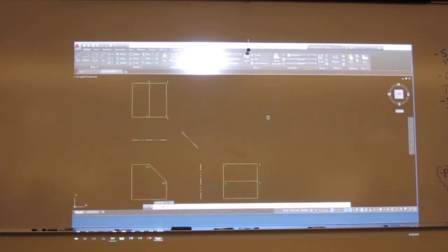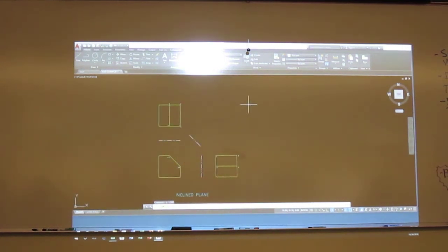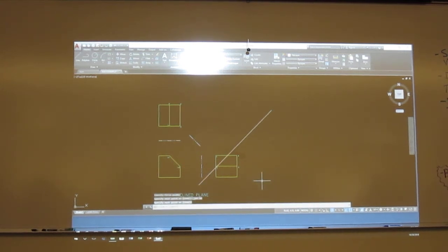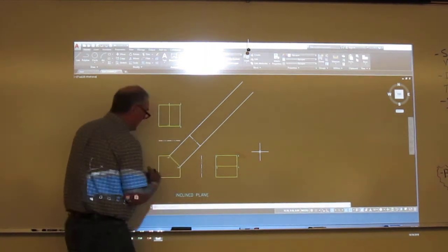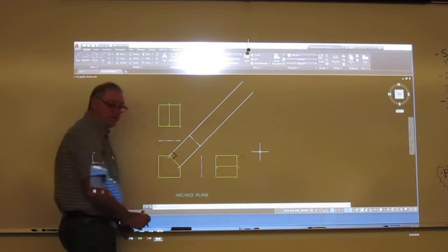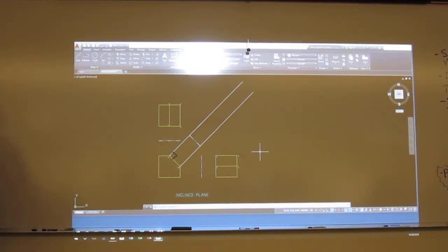All right, so the first thing I want to do is create some projection lines. The way I do these, I just get out way far, click a line, use my perpendicular snap to that plane, so that line's perpendicular. Then I'm just going to move that to the point in question and copy it to any other points I might need. In this case, we really only have 2. Now you want to make sure, folks, when this comes in, this line must be perpendicular to the plane you are looking for.